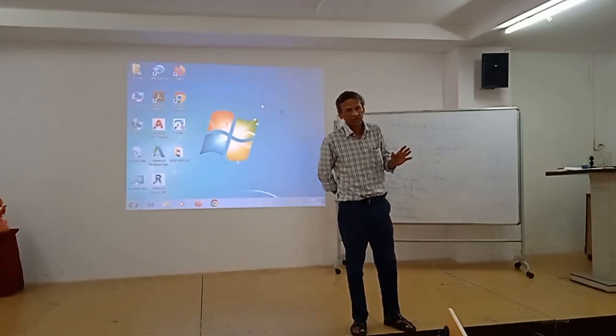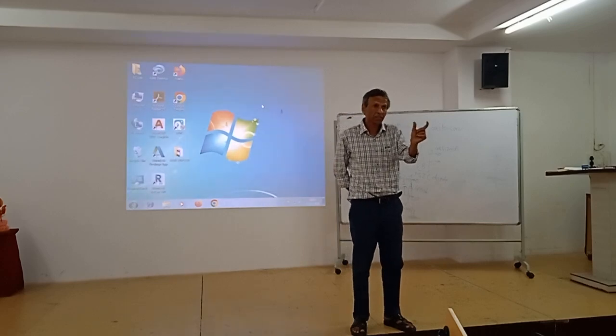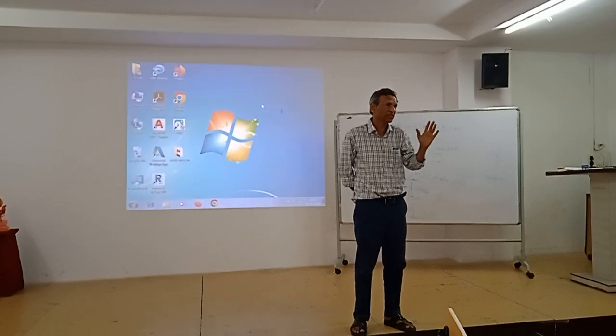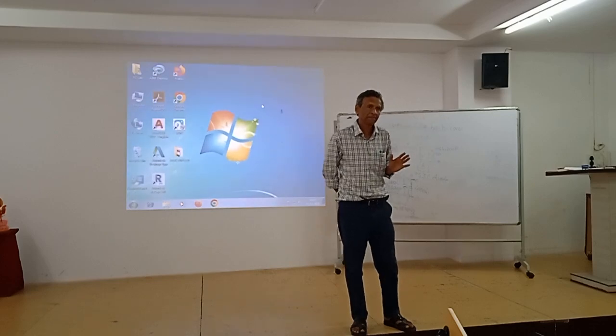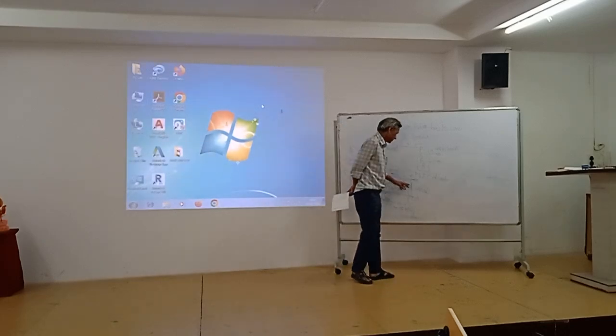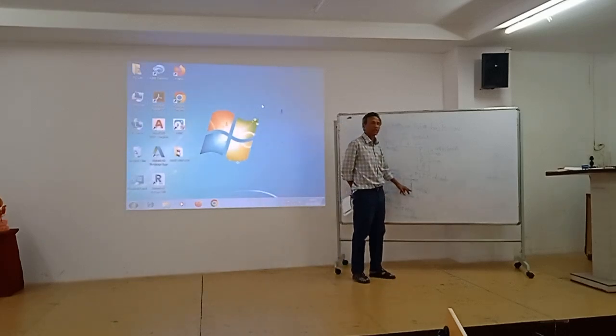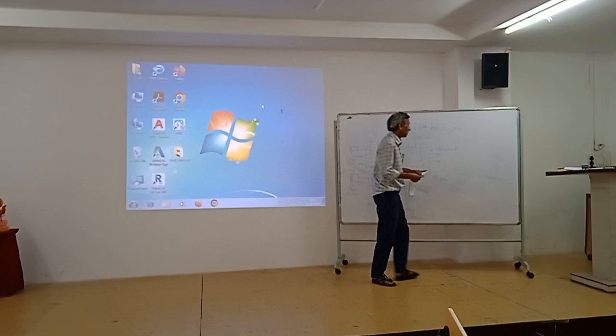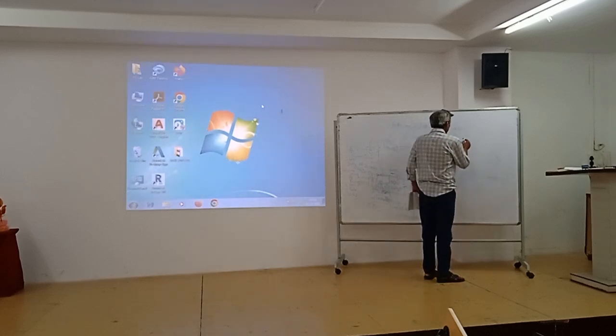That is the nameplate specification. So if you make it 48 volt working, it will be the best operation, higher efficiency, everything. So how to get 10 kilowatt supply from 400 volt to 48 volt? There is something called phase shifted full bridge, one of the topologies.